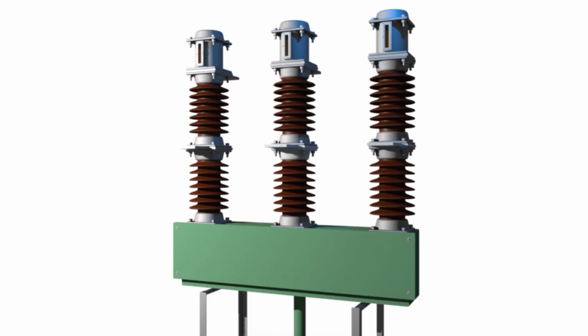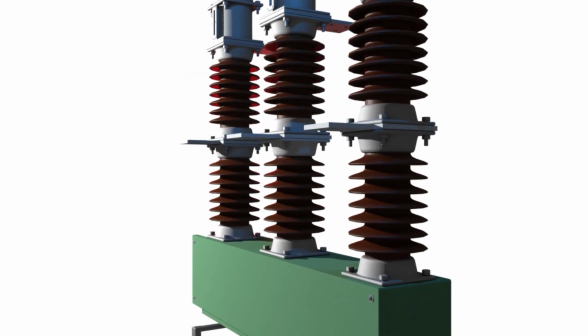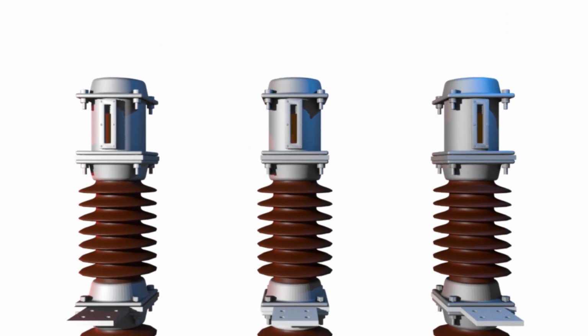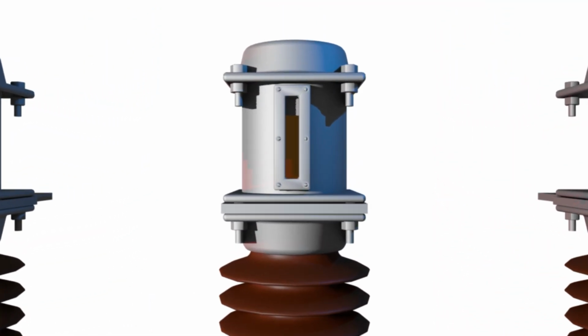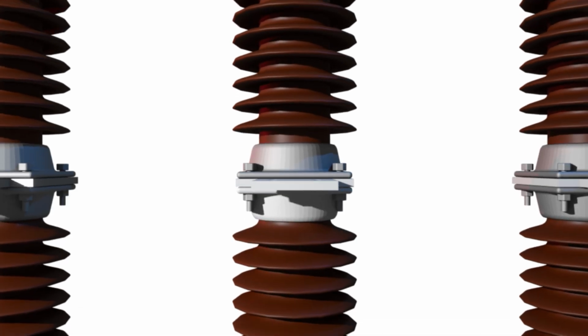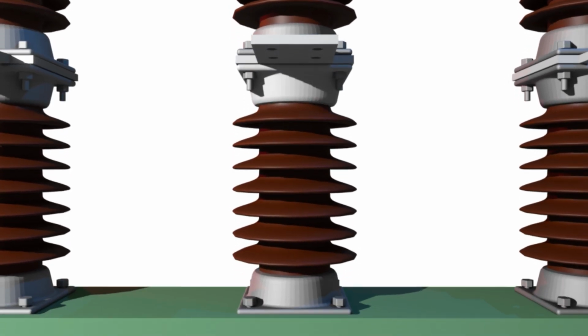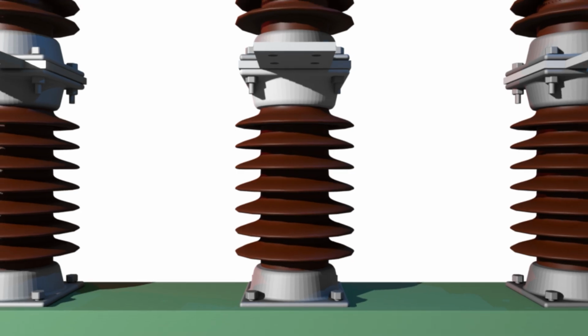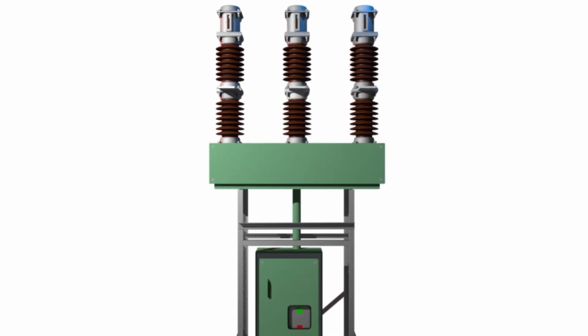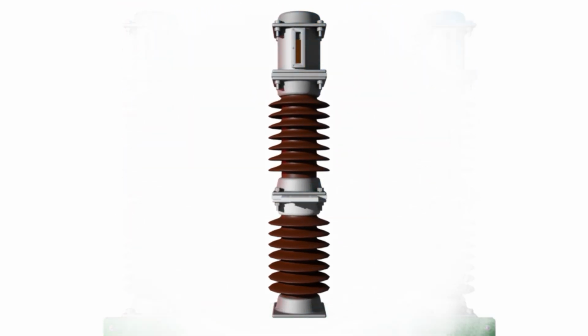So there are three chambers. One is the top chamber, which provides the required vacant space above the oil for accumulating decomposed gas during the arc. The middle chamber, which we sometimes also refer to in general as the top chamber, contains the current interruption mechanism, and the third chamber is normally a hollow cylinder of porcelain insulator that also contains oil. We also fill that chamber with oil. But this oil does not have any direct relation with the oil of the arcing chamber.